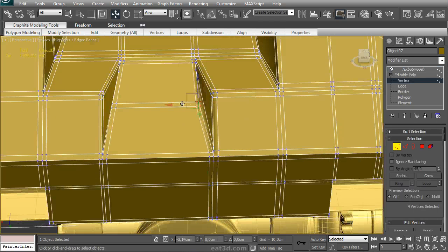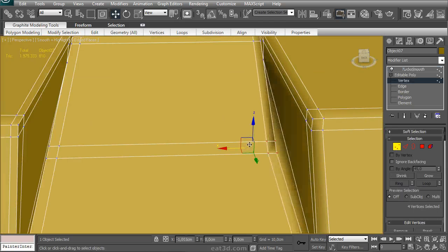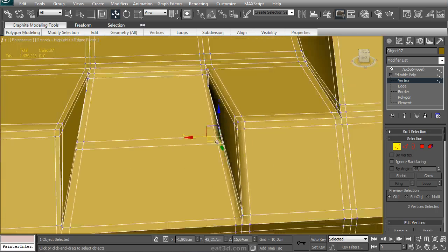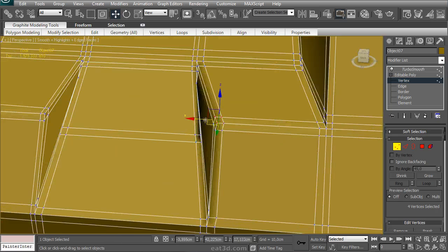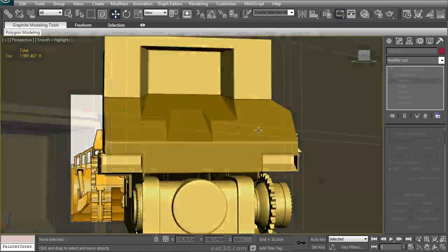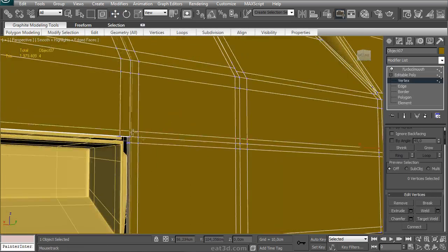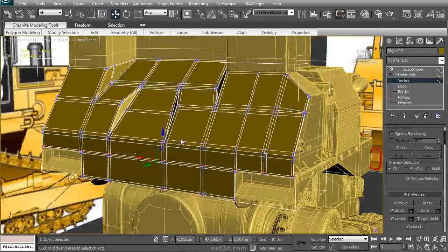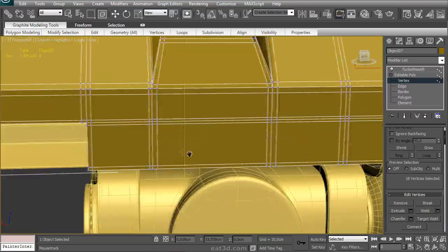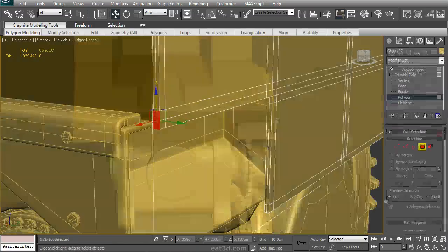All right, need to move these around a little bit. Messes up the smoothing slightly. As well, not everything is aligned in a single plane anymore. Doesn't matter so much, even though this is a little bit sloppy, because Turbo Smooth will fix these minor problems, which is why I'm leaving it like that. Alright, that's the extra edge I was talking about. Over there.